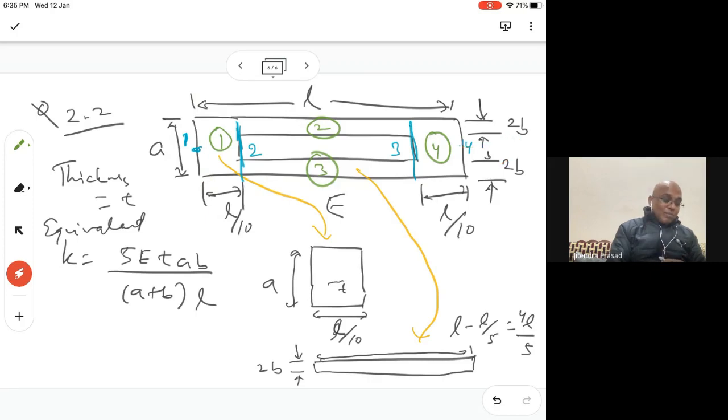So we are going to fix this and give U4 equal to 1, and we have to find F4. This F4 will give us the equivalent stiffness, because U4 is 1. Whatever force we get has to equal a stiffness, the force required per unit displacement.